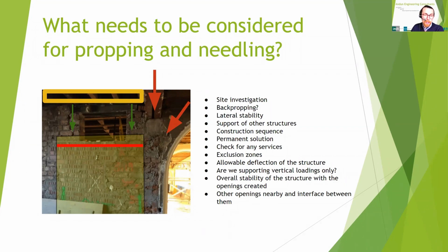On some schemes, we stipulate that openings are carried out and completed on one floor before you move to the next floor, or certain openings open at one point and not the other. This is just to mitigate some risk against global instability, really. And there are other considerations that will be project specific, but if you plan ahead and get some engineering input on the design at an early stage, then the work should go nicely.